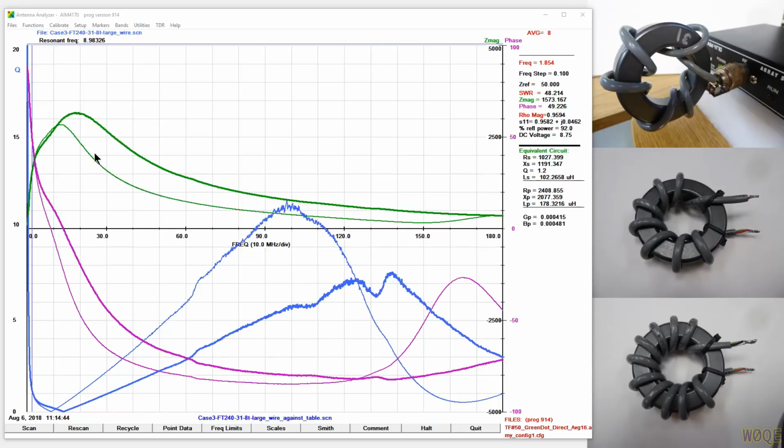And if you wind for this incredibly high impedance and you measure it on an analyzer and you put it in a circuit and you lay it down on a table, lay it down behind equipment, other wires are nearby, you will see a lesser performance than you would have seen otherwise. Now, it turns out that the impedance reduction you see is less if the core has less impedance. What that means basically is if the core isn't very good, it doesn't get hurt much by putting it on a table. A metal table is even worse. But this is something to definitely be concerned about.